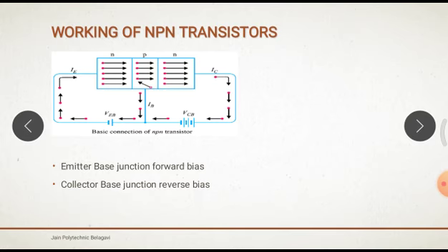Before I start with this, we have to give the supply voltage, a DC supply, to the transistor. It is called the biasing of the transistor. Biasing of the transistor works in three regions: one is the active region, the cutoff region and the saturation region.